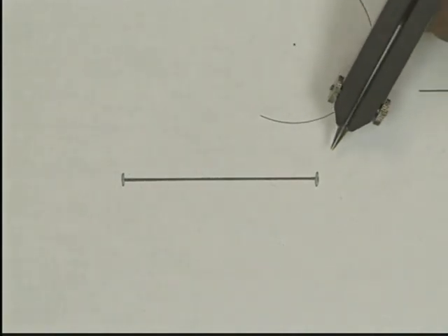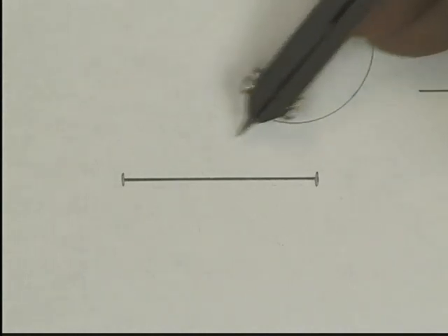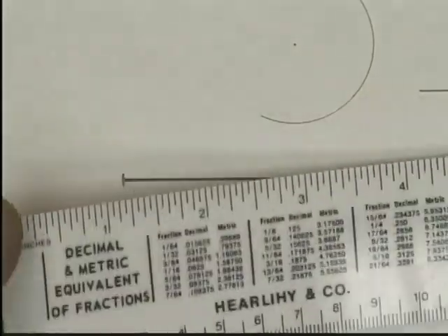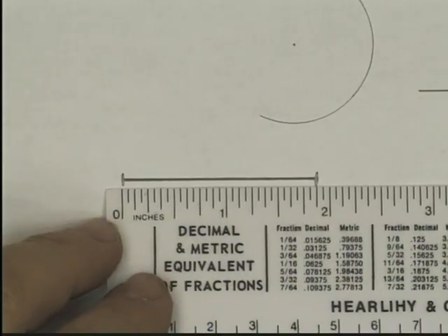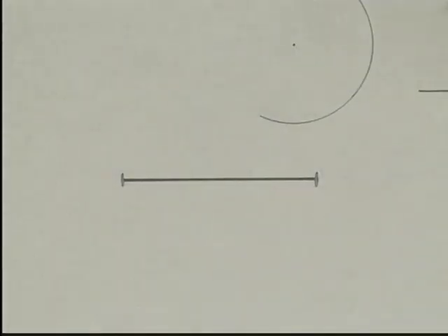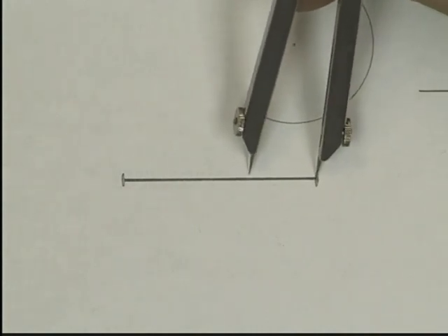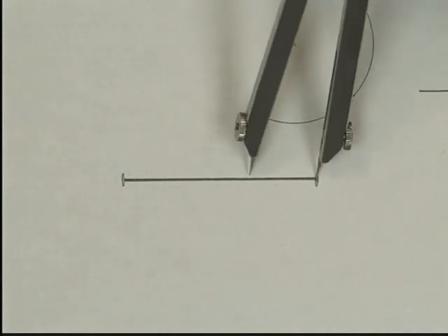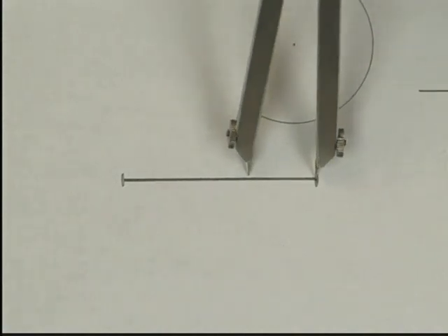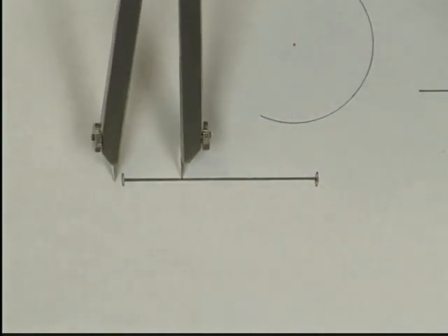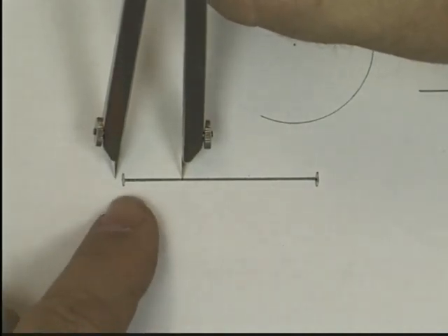There are several different construction techniques we can use to actually divide lines into equal spaces. And chances are that we're going to run into lines where we don't want to do it by measuring the line and then doing some math. Might be faster to use the dividers and the so-called trial and error method. I want to divide this line into 3 equal spaces. So here's what I do. I make a guess. I put this dividers on here and I say, I think that's about 1/3 of that line. And so let's check. There's 1 division. I just put the point in, rotate it. 2 divisions, 3 divisions. Whoops, I guessed too big. I don't know if you can see, but I've got a little extra there.